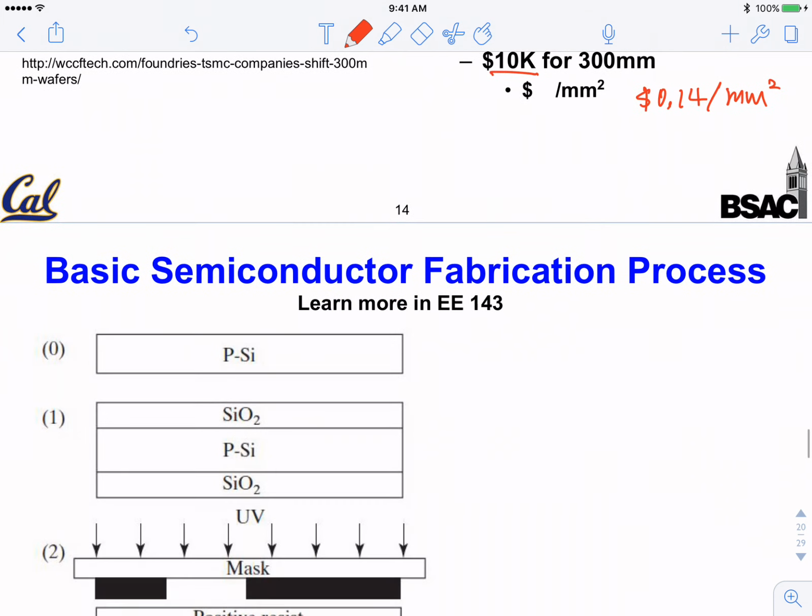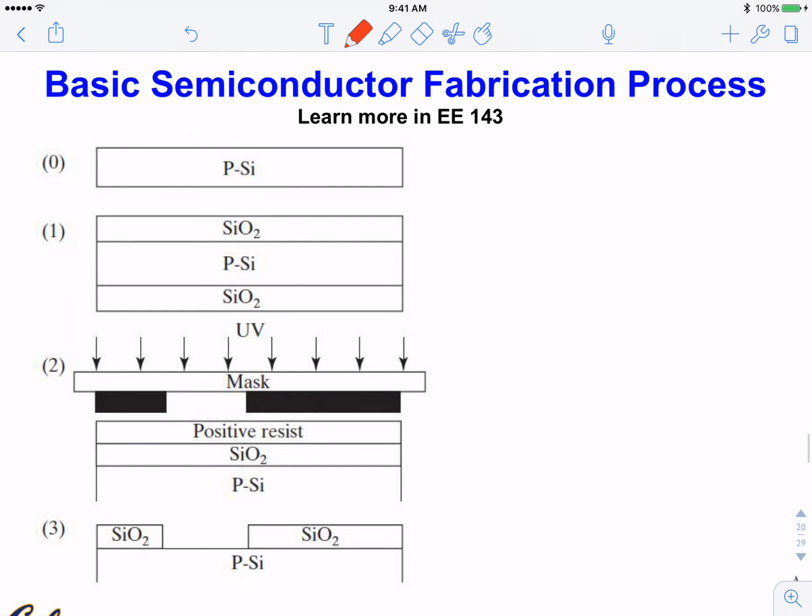So what goes in there? Okay. It's a repetition of the following process here. So you start with this wafer. This is the 200 millimeter or 300 millimeter silicon wafer that you started with. Okay, and you repeat the following steps. One is deposition. You add materials. Add material, this step is typically called deposition, okay?